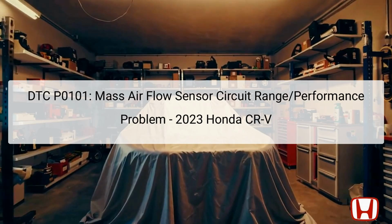Located typically in the intake air system, right after the air cleaner assembly, the MAF sensor can be affected by several variables, including wiring issues and blockages in the intake system. Addressing DTC P0101 quickly is essential to maintain vehicle performance and ensure compliance with emission standards.